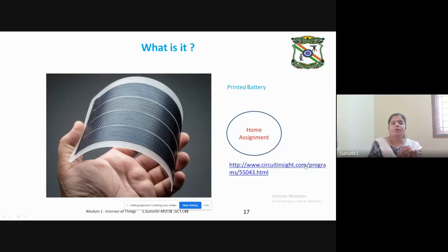First you remove the noise from the weak signal, then you amplify the strength of the signal, then you pass it to your ADC to get your digital signal. That means digital values, right? And then these digital values can be processed by your DSP.